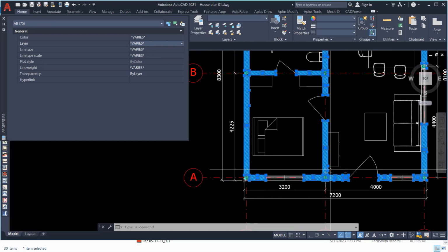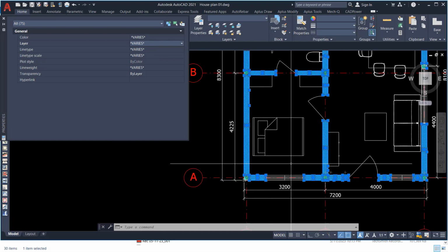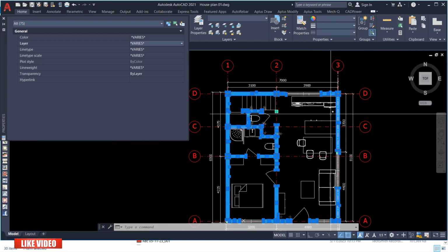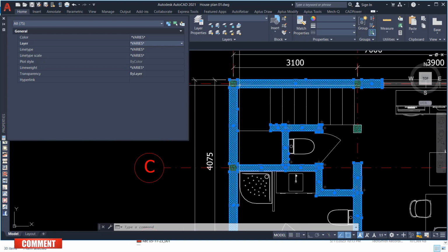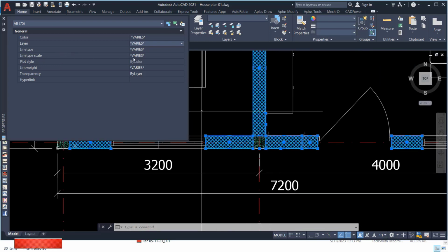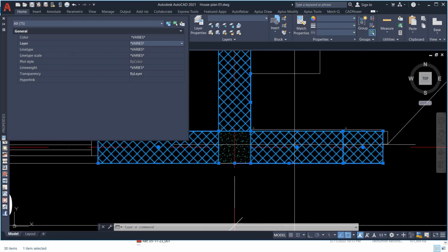So we want to pull it from that layer into this new layer here. Prior to doing that, make sure any layer that has been assigned is not included into a different layer. As it is now, we are okay. The reason it varies is because the hatches have been assigned a different layer, and we want to bring it from that layer into a new layer here.